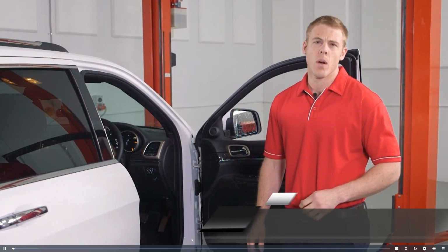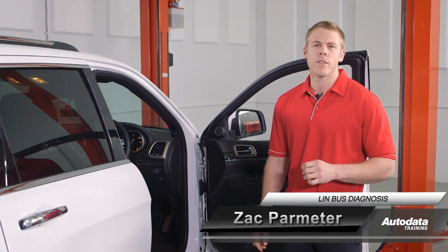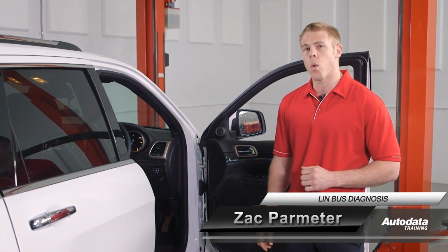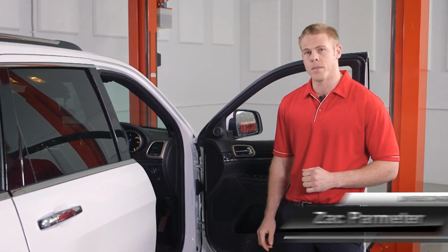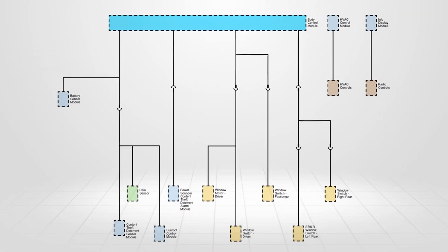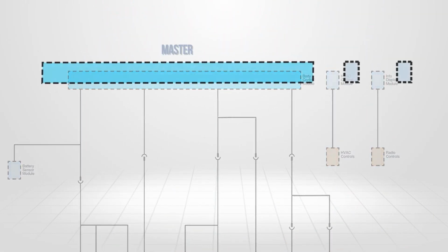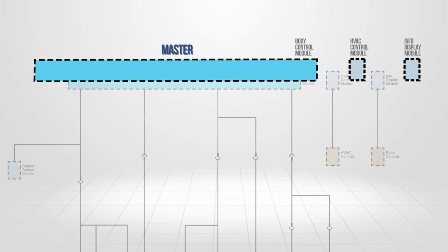Reduced cost, wiring simplicity, and relatively straightforward maintenance are a few of the reasons why LIN bus is incorporated into the modern-day automotive system. LIN works on a master-slave basis. The master in most cases will be the body control module or the module responsible for that node.